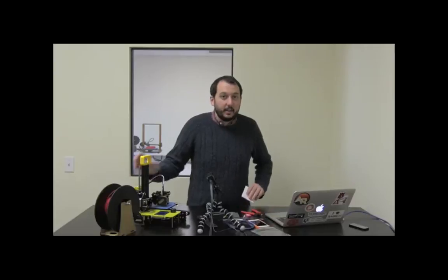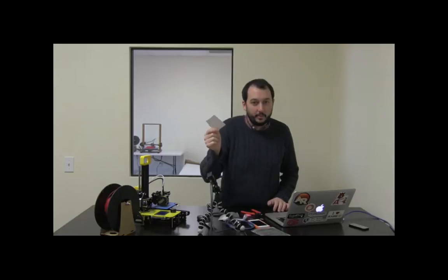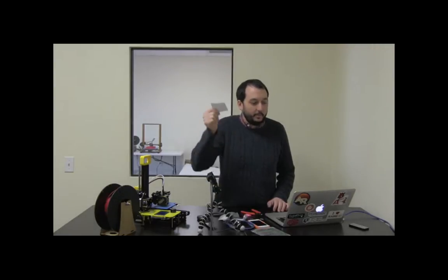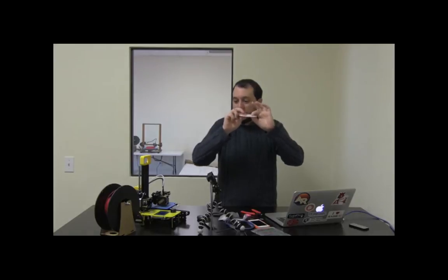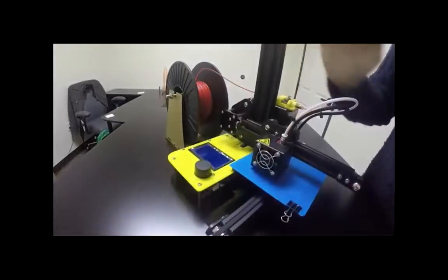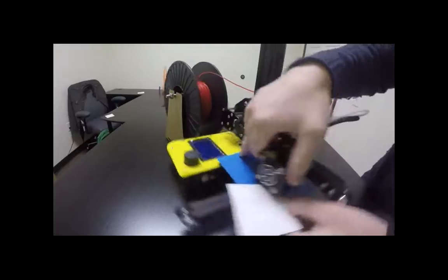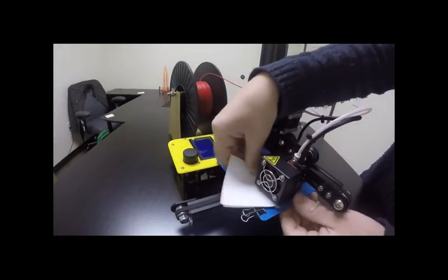You're going to take a piece of paper, and I'm just going to use this small piece of paper, but you can use any sort of scrap paper if you guys want to get a piece. Because you're going to put this between the nozzle and the build plate and then move it, and you want to feel the tension on the piece of paper, but not so much that it buckles. And you want to feel that underneath each one of the little wing nuts on the bottom of the printer itself. So you can see little nuts underneath here. That's what you adjust to adjust the build plate. So you'll put the piece of paper between the nozzle and between those wing nuts, like this.